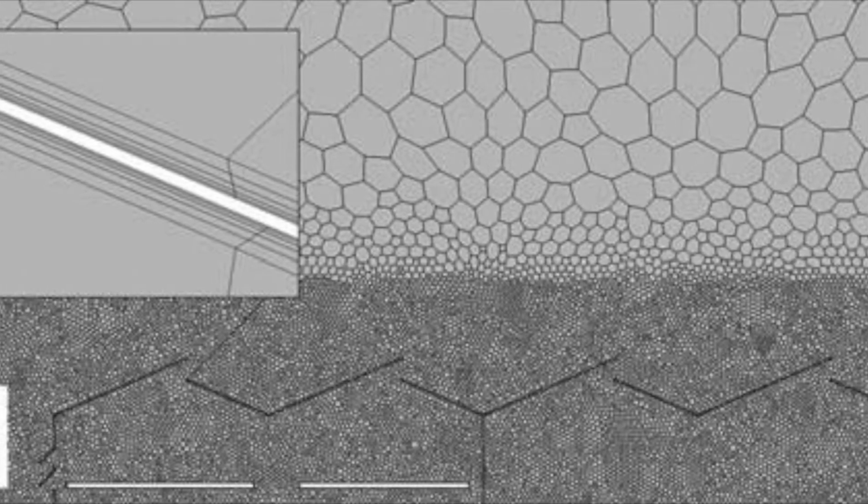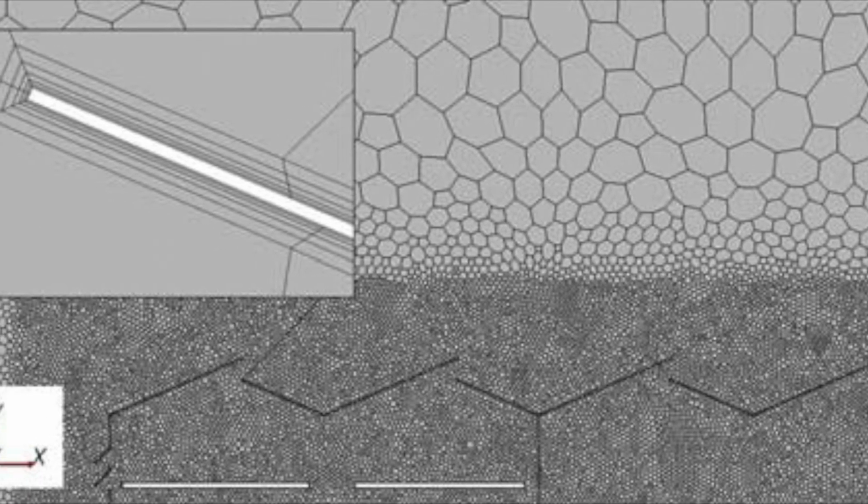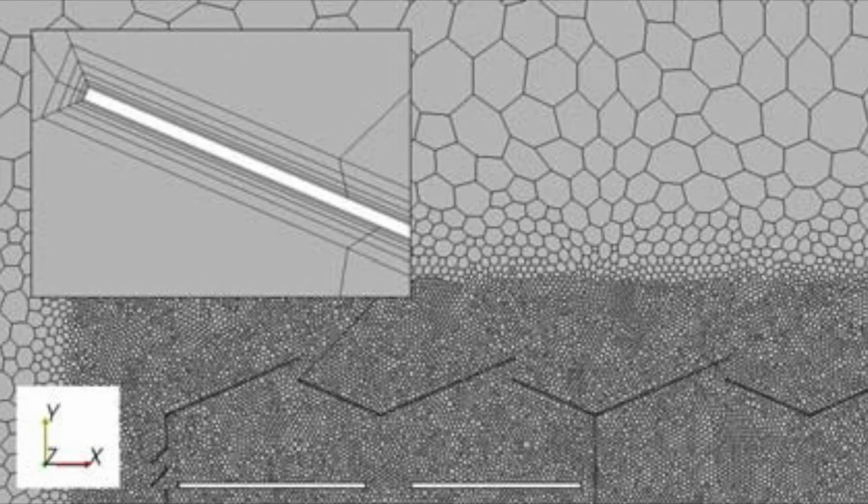To capture the hydrodynamic boundary layer in the correct way, we use the prism layer measure, where prismatic cell layers are located near the different wall boundaries. The embedded thin measure option was selected and the thickness threshold option was enabled, which allows monitoring of the modeling of the hot fluid tubes. Before running, it was necessary to define the physical model that described the behavior of fluids in the heat exchanger.